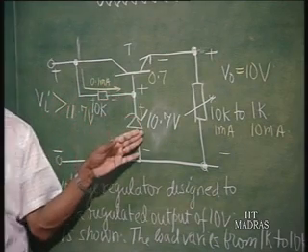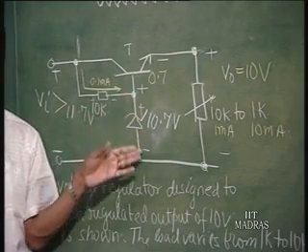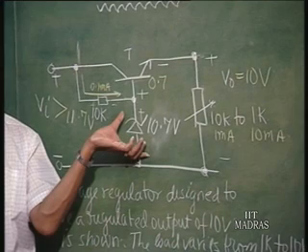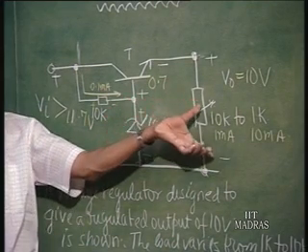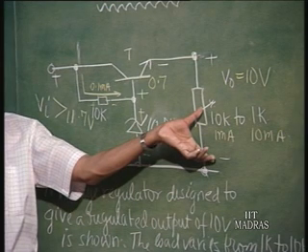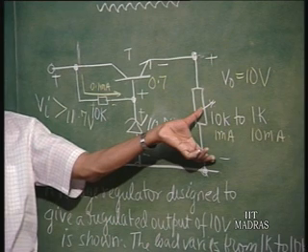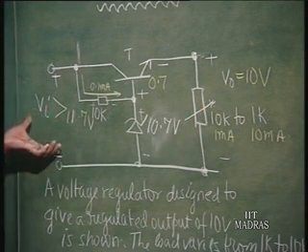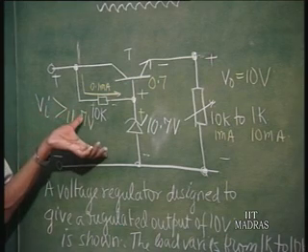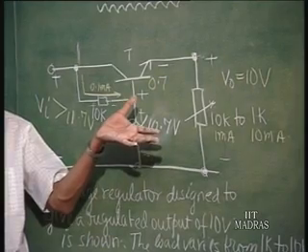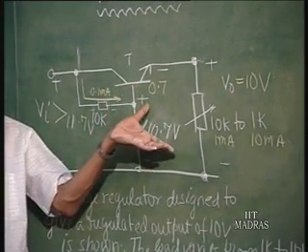As the Zener current changes from 0.1 milliamperes to 1 milliampere, find out the change in Zener voltage. Okay. That is delta Z, let us say. That divided by 10 is going to be the ratio change in output voltage, okay, and the input changes from minimum to maximum. That expressed as a percentage is going to be the line regulation factor.